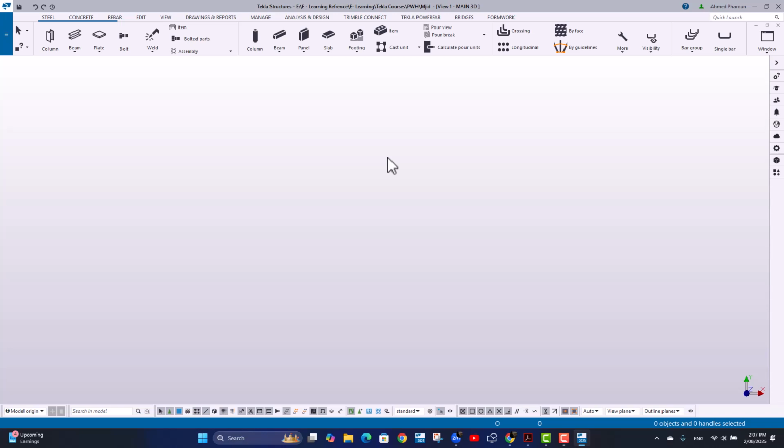And the third category, which is plates and slabs and any other types, can be specified by three points or more. Yes, it's a slab, it's a surface. So you can identify a surface by three points or more because it's identified by a plane. Other than this, it's a beam or a column. So a bracing in Tekla is a beam. Anything that can be expressed in two points is a beam. Anything that can be expressed in one point is a column.